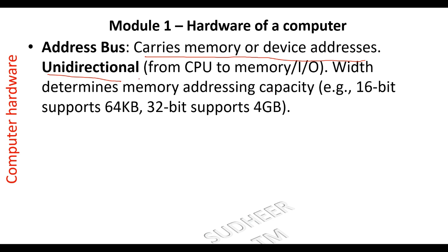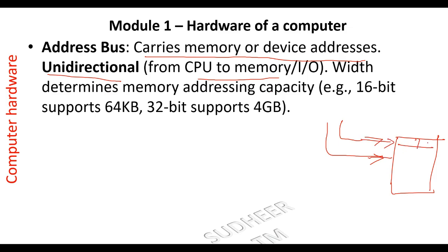Address bus is unidirectional, from the CPU to the memory only. Whenever the processing system needs data, it will initiate the step to send out the address of the memory. Whichever room is selected, this is the first memory unit, second memory unit, third memory unit, fourth memory unit, to the last, nth memory unit. Suppose I want data from the mth memory.